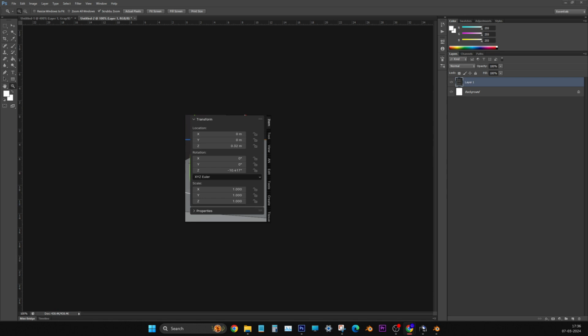So if you want to check whether there is only one vertex or two vertices, you can just select there, pick select, go to move option and move it and see only one vertex is there. Yeah, right, undo, immediately undo. Now, okay, Alt A, deselect.